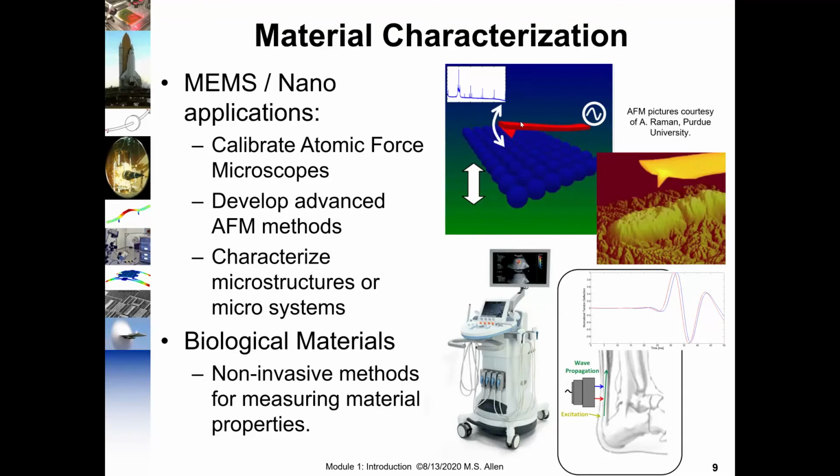And one of the most sensitive ways to use this device is to actually cause the tip to vibrate steady state over a sample, and then monitor the phase and the amplitude of vibration. And then we sweep this tip over the surface while holding, say, a constant phase or a constant amplitude of vibration, and you can get incredibly high resolution images of surfaces.